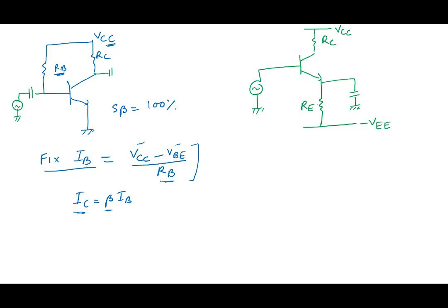What is the strategy here? What are we doing here? Now note, in this case, if you were to do the biasing part, what will you do to the signal? If I were to look at the biasing of this particular circuit, what happens to the signal? Signal will become ground. For bias analysis, you'll put it to ground, right? And capacitor you will open. All right, capacitor you'll open, so you'll get this.